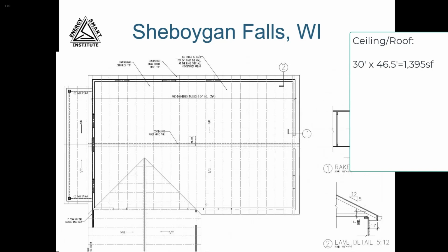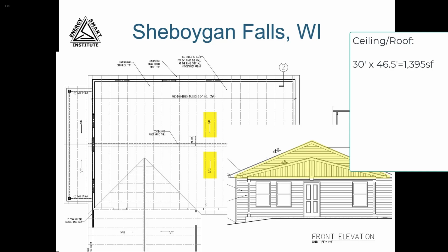Let's take a look at the roof plan. We can see that the roof over conditioned space is a 5/12 pitch with a center ridge and a gabled end on the front and the back. We can ignore the garage because that is built over the roof decking of the house, which is where our foam insulation is going to be located. To determine the area of the roof and gable walls, we need to pull out that old Pythagorean theorem.